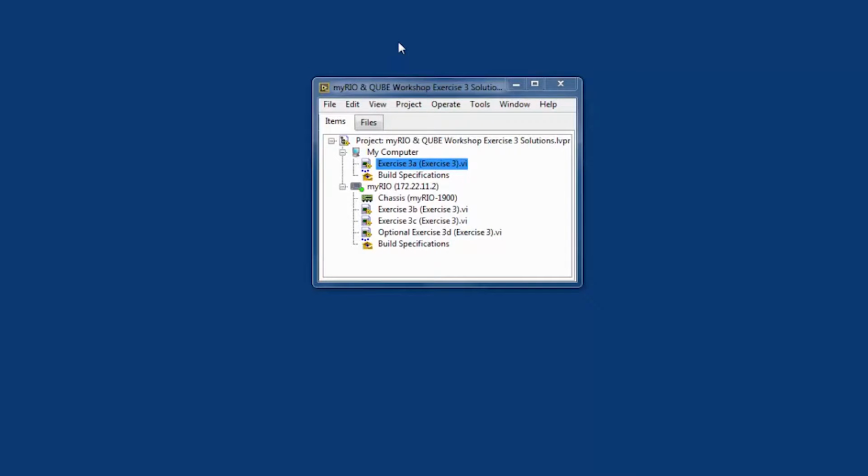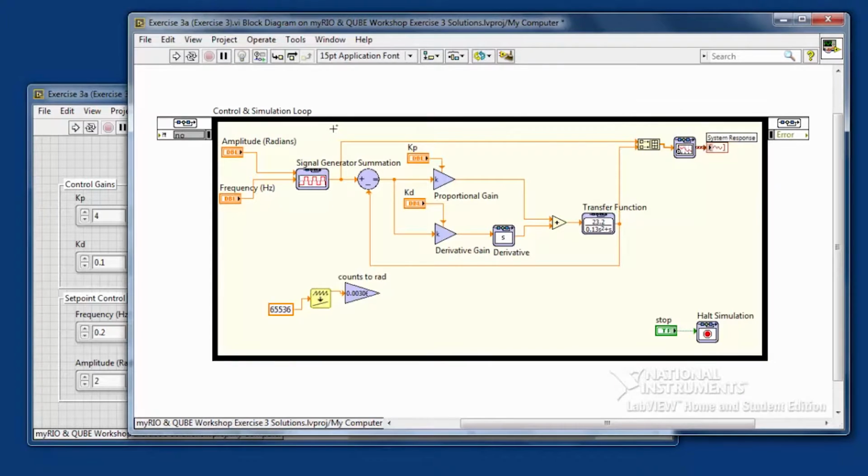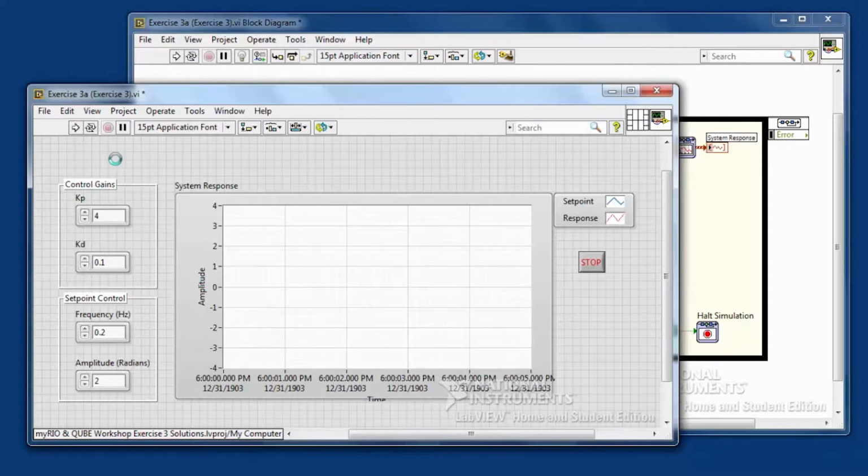So let's go ahead and use some software that mimics what you might find yourself drawing on the chalkboard. In this case, I'm using LabVIEW. So let's go ahead and open up that simulation. Now if I jump to the block diagram, you see that LabVIEW is being used to implement a mathematical plant model so that we can tune our algorithm based on a representation of a real control plant. I can even choose from a wide variety of solvers, allowing students to learn the implication of each solver type. Now if I jump to the front panel again, I can run my simulation,